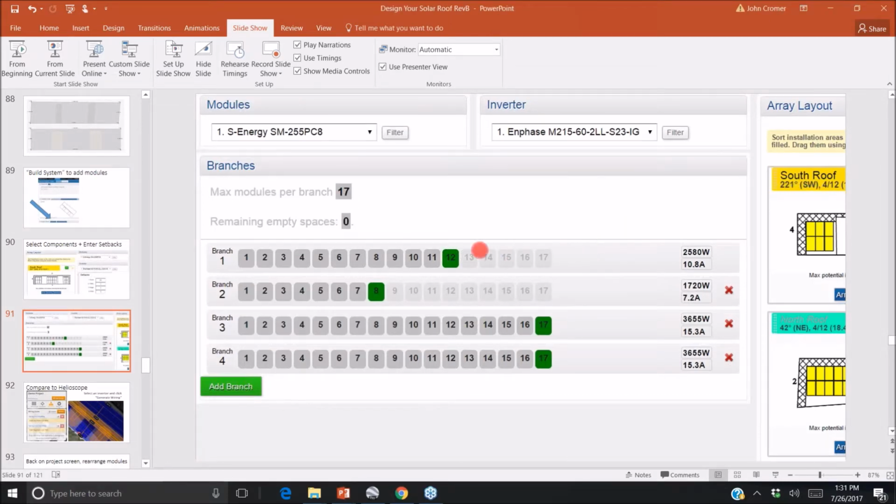So here we have two different surfaces, the north side of the roof, the south side of the roof. The south side of the roof is smaller than the north side of the roof. The north side of the roof, we're doing 17 modules across. And if we fit 18 modules across instead of 17, I would probably not do the extra modules. Keep it optimized for this particular system. 17 modules across on the northeast section, and then on the southwest section, we're going to do that one middle section of 8 modules, and then the 2 side sections of 6 modules on a shared circuit.